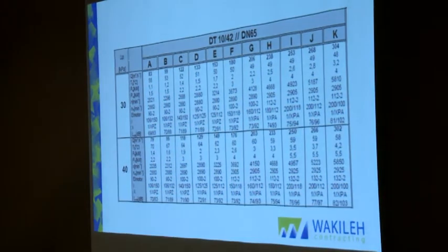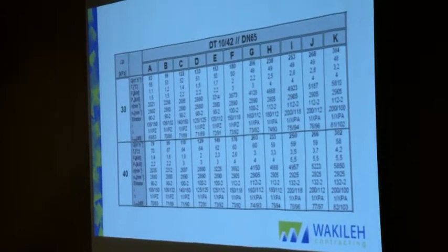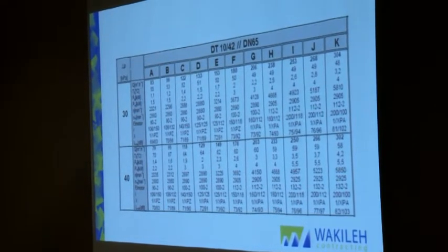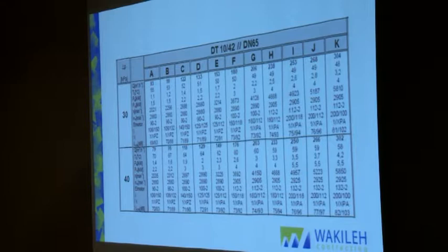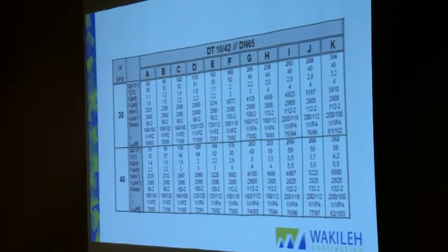In the specification, it has to be specific at what speed I have to run. Otherwise, people will tend to offer you the highest speed. With the highest speed, you will get more heating, and then the lifetime of the equipment is reduced.